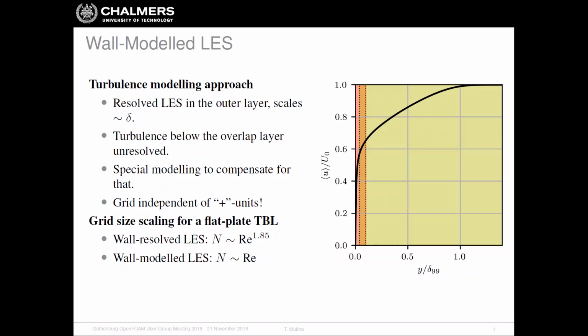And the idea of Wall-Modelled LES is basically that we're going to resolve all the turbulent structures as in normal, what I will call wall-resolved LES here, in the outer layer, so up to this point. But we're not going to resolve the turbulent structures in the region of the inner layer below the overlap. So we're not going to resolve the turbulence in this pink rectangle.